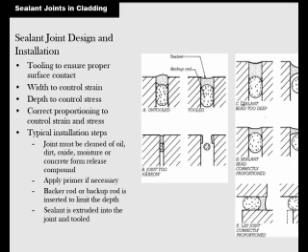Because you have to have the proportions correct. Here the sealant bead is too deep. The sealant bead here is correctly proportioned. It will expand and contract. And a lap joint correctly proportioned.